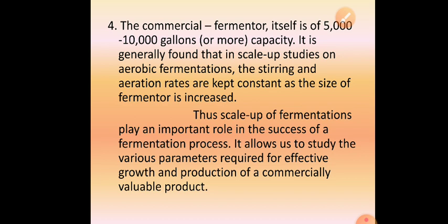It is generally found that in scale up studies on aerobic fermentations, stirring, that is mixing, and aeration rates are kept constant as the size of the fermenter is increased. That means the rate at which mixing is done and the rate at which air is pumped inside, that means aeration and agitation, are kept constant as the size of the fermenters goes on increasing.